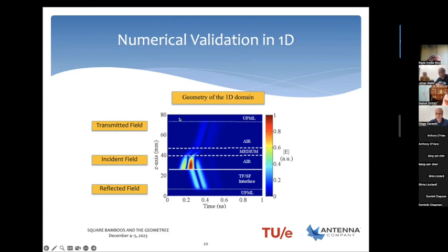You can also notice at the top and at the bottom of the computational domain the effect of the UPML termination, that, as I mentioned previously, enables a nearly ideal absorption of waves. And this is important to simulate effectively the extension of the computational domain to infinity.